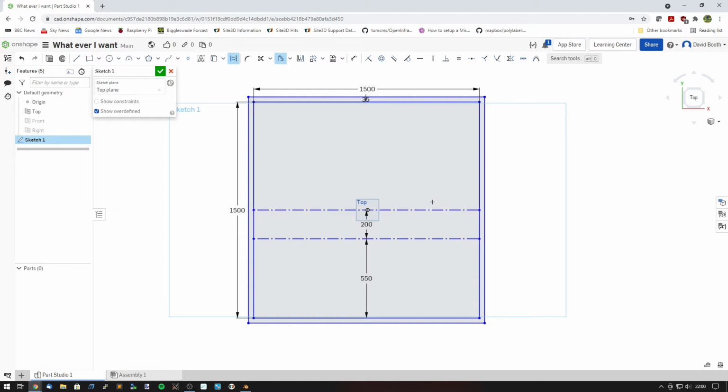Now the next thing I have is the actual feed the fish rectangle up here, and the front face of that is 360mm off. So I can select this one, change the direction, left click again, and this one is, as I said, 360mm from here, and the left hand side of this rectangle that's going to be up here is 650mm. So that's how I can do that kind of thing. The other way I can do that is by just drawing a rectangle and then offsetting it from that. But actually, let's do that.